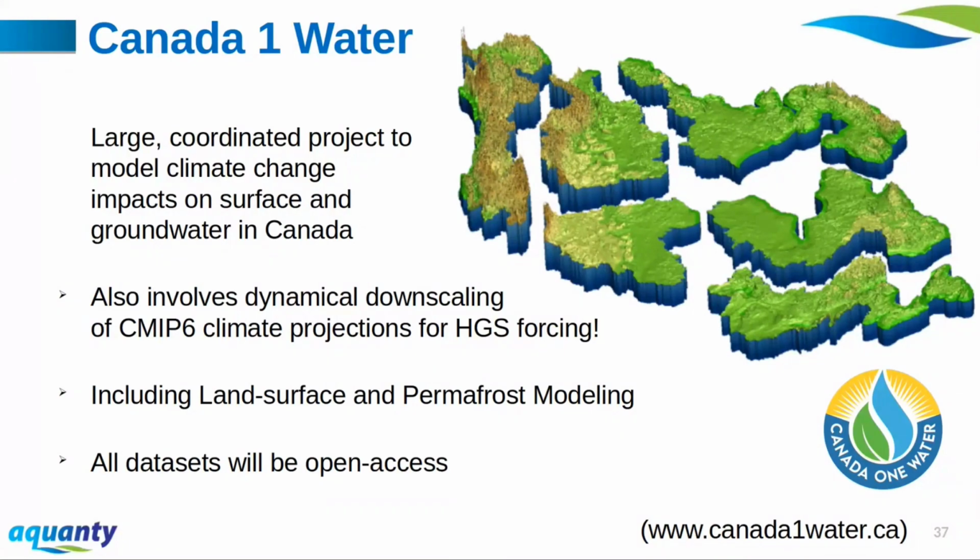The data sets themselves will be at higher resolution than we will run the large basin scale models, and most of them will be high enough resolution that they will be suitable to just carve out a little area of that and run a higher resolution model, something like the Grand River model or even higher resolution. So a lot of the input data sets will actually be something like 300-meter resolution, right? Like the DEMs, even higher resolution. So this will really facilitate carving out small models and zooming in, but also building larger models and having them based on a consistent database, right?